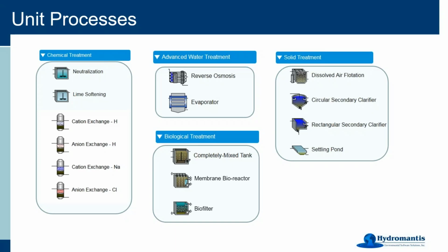On the solid treatment side, we are, of course, not only concentrating on the liquid side, but we are also managing the solids that are being produced, and we can look at how you manage your solids in the system. There are dissolved air flotation for thickening the solids, some settling ponds, and some dewatering and thickening unit processes that can be utilized for handling your solids.